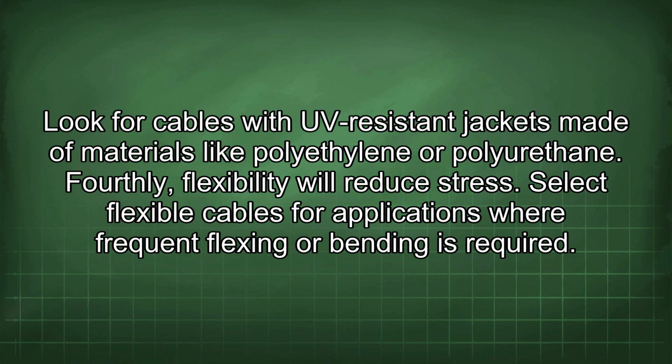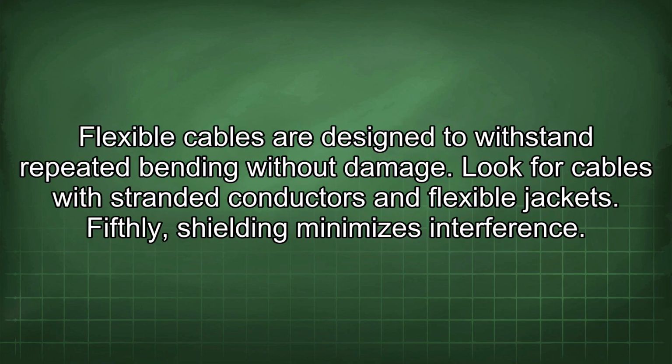Fourthly, flexibility will reduce stress. Select flexible cables for applications where frequent flexing or bending is required. Flexible cables are designed to withstand repeated bending without damage. Look for cables with stranded conductors and flexible jackets.